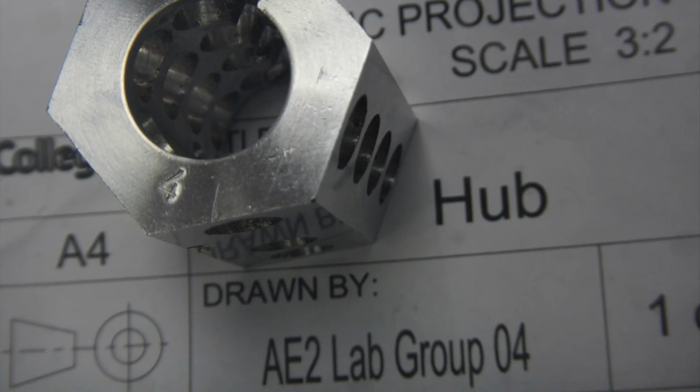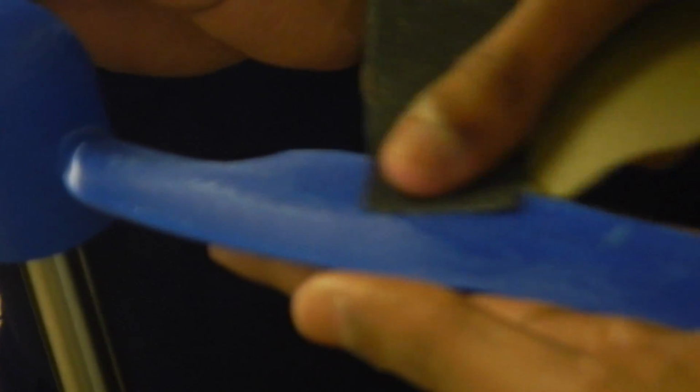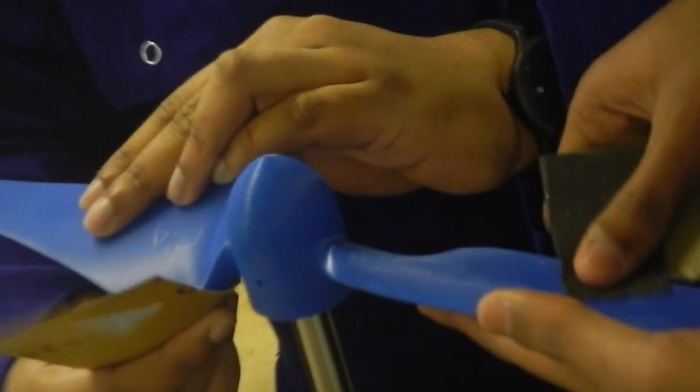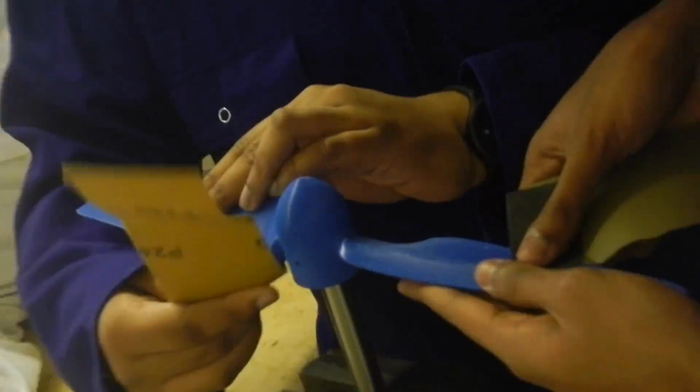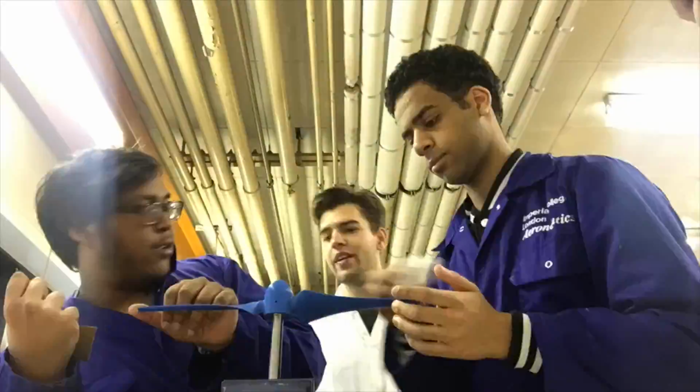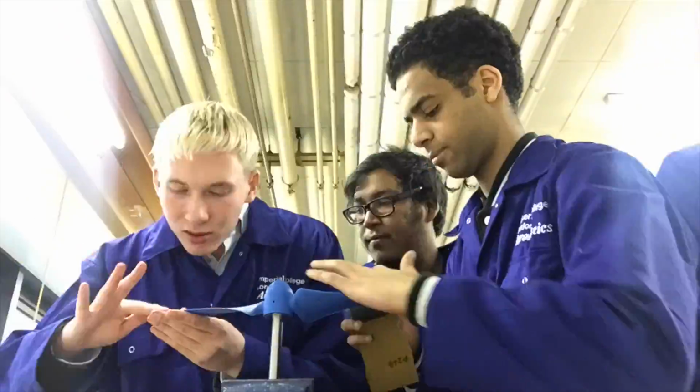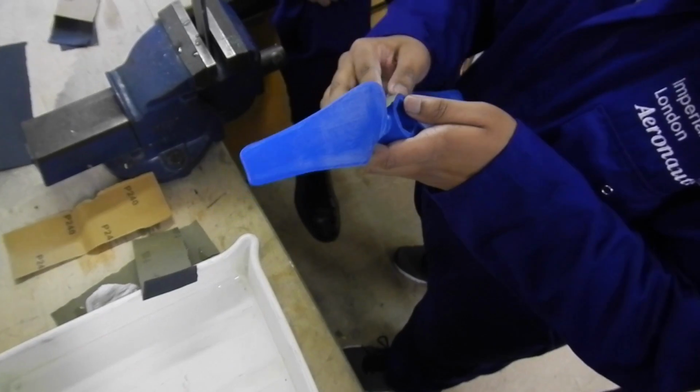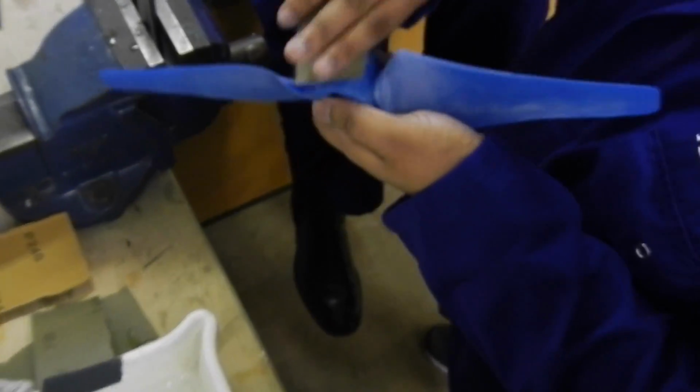After assembling the printed blade and aluminum hub attachment, the final part of the manufacturing process was to improve the surface finish by hand sanding the blade using a series of increasingly finer grit sandpapers. There was a small inconsistency on the surface of one of the blade tips, and we mitigated this by applying some clear lacquer to the defect and then sanding it back to match the intended blade profile. Our blade was now ready for testing.